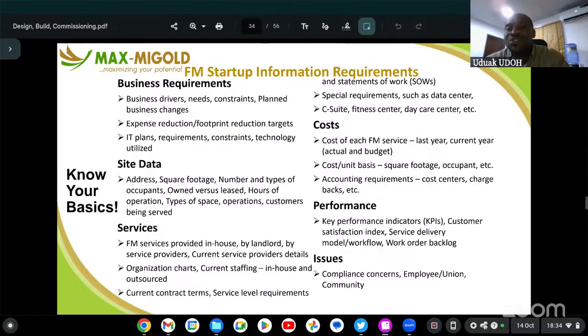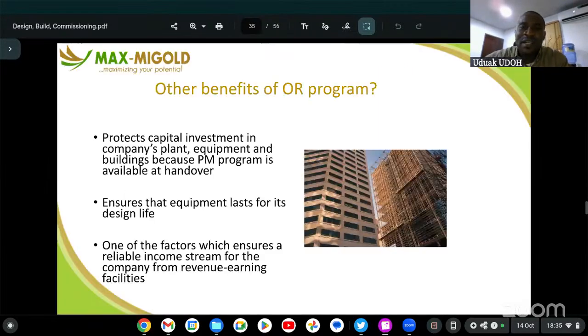Then we should also check for backlogs, logs that are pending, some deferred maintenance that has not been approved or treated, and it's causing issues. It could just be a flickering bulb, and it's not an issue now because it's inside the store. We go there once in a while, so there's no need for us to change it. We should always check for that and correct the defect on time too. And therein, we could also see other benefits of an operational readiness program.